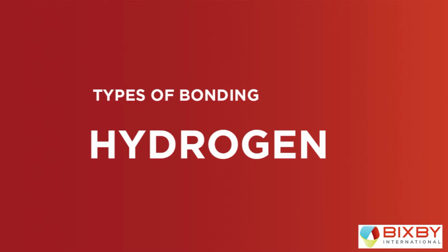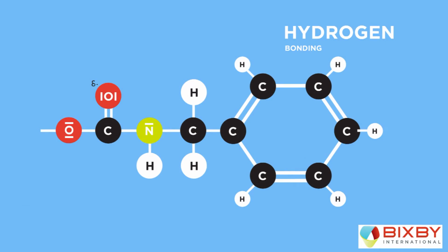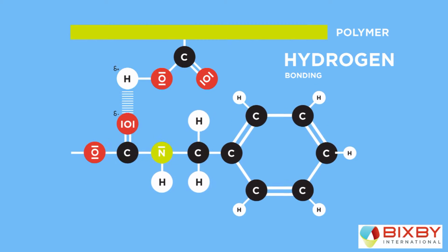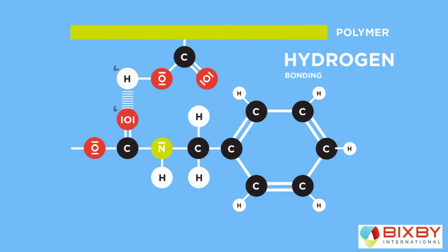Another type of chemical bond that can be developed at the surface of two substrates is, for example, the hydrogen bond. Hydrogen bonding is a strong dipole-dipole interaction which occurs when a positive end of a group is attracted to the negative end of another group. Polymers with carboxyl, acids, amines, amides, or hydroxyl groups can therefore create hydrogen bonding with other polymers. We may have this type of interaction, for example, when we corona treat a polyethylene film that develops a carboxylic acid group on the surface and reacts with the oxygen of a urethane tie layer.